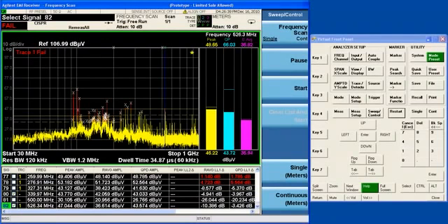You can save the ambient signal list and then load it in every time before you start the test, because when you do a search with an existing signal list loaded, it always adds the new signals that it finds to the signal list rather than overwriting the existing signal list. So that's basically the way the final measurement works.